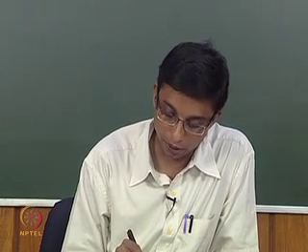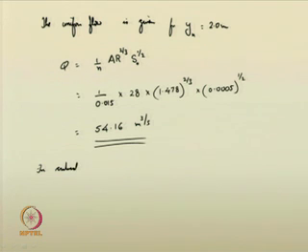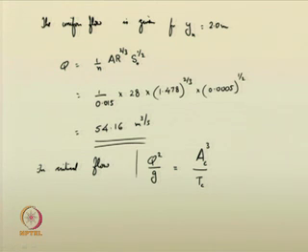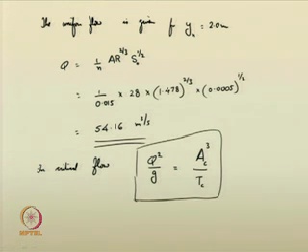You have to identify whether the flow is critical, subcritical or supercritical. What is the procedure? For critical flow, you recall from module 1, you had the relationship Q squared by g is equal to the area of cross section at the critical depth cubed by Tc, that is the top width at the section where the depth is critical. This relationship is uniform for all types of channels, whether rectangular, trapezoidal or triangular, you had seen them. So, you have to use this relationship again here.